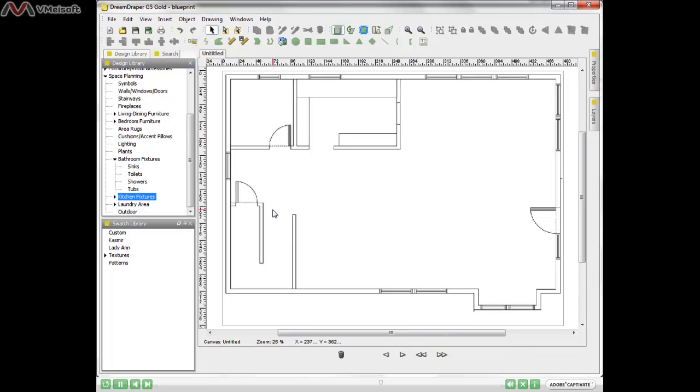In our last example, where we had a simple rectangular floor, we filled that with a wood grain. Well, if you wanted to fill most of this floor with a color or a wood grain, that's no problem. I'm going to use one of the drawing tools. Now, I could use the cubic Bezier or the polygon tool or the polyline tool, but in this example I will use the cubic Bezier. So I'm going to click on my drawing tool, and then I'm going to start clicking along the perimeter, and every time I turn a corner I'm going to click.